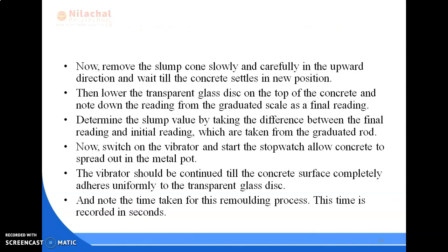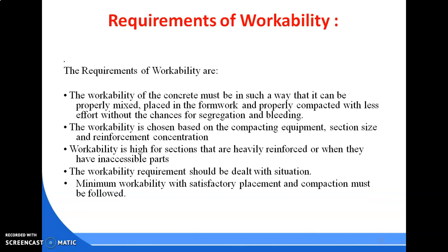So these are some procedures available to find out the workability of freshly mixed concrete. The last and most important thing is requirements of workability. So let us discuss the major requirements of workability. The workability of the concrete must be such that it can be properly mixed, placed in the formwork and properly compacted with less effort, without chances of segregation and bleeding.